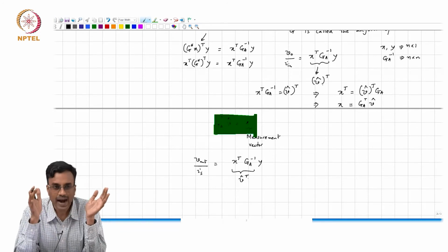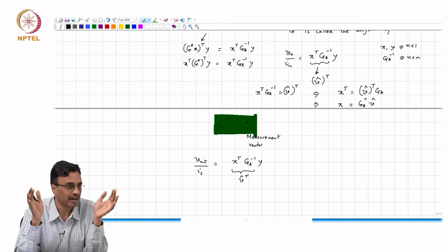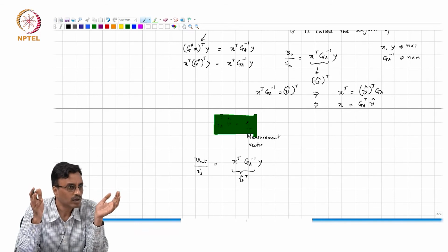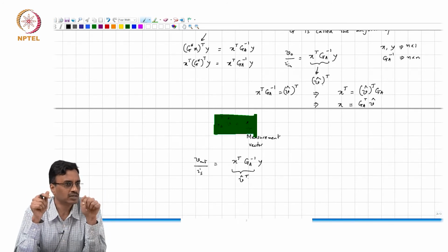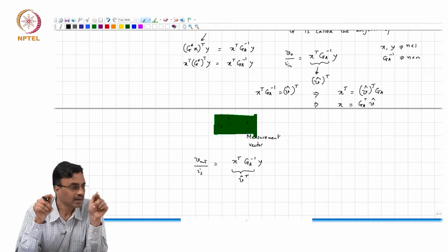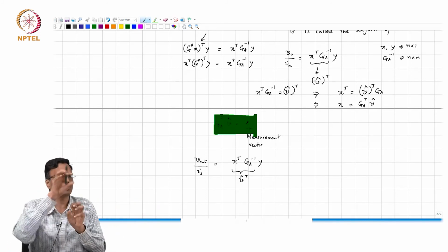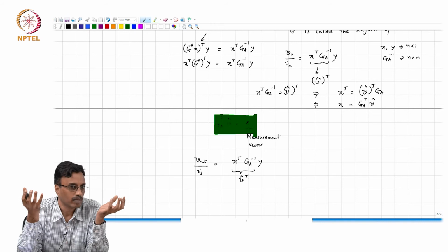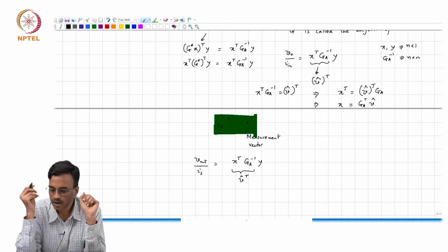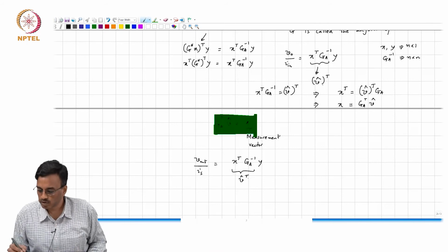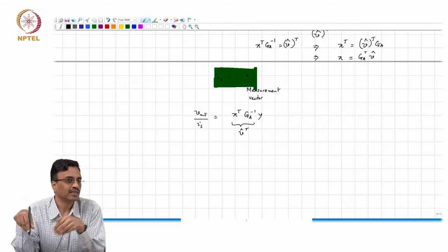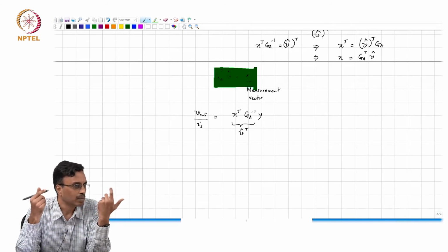So, in other words, V hat transpose, that row vector, contains information with regard to all the transfer functions from all the inputs to a given output, right? And this Y merely selects which of those transfer functions you want. Therefore, if you want multiple transfer functions to the same output, this obviously entails a lot less labor, because you're solving